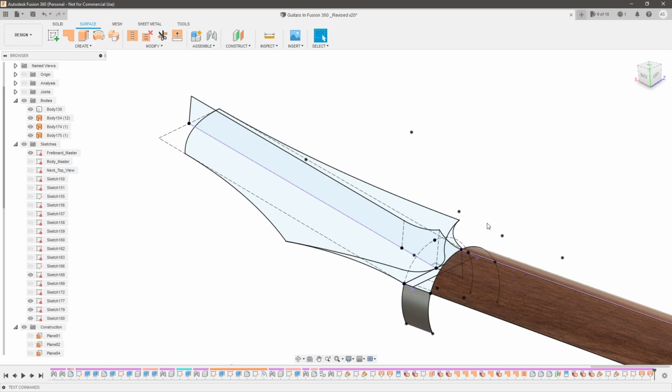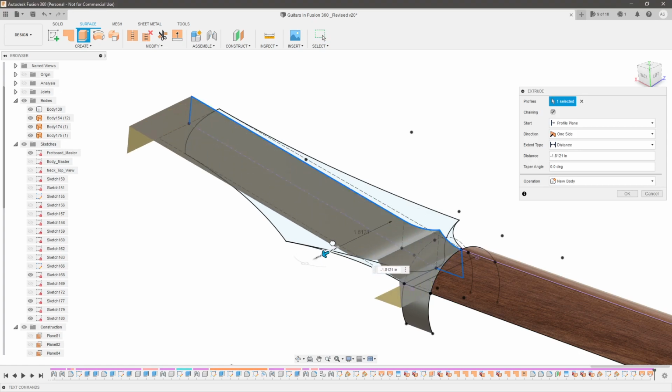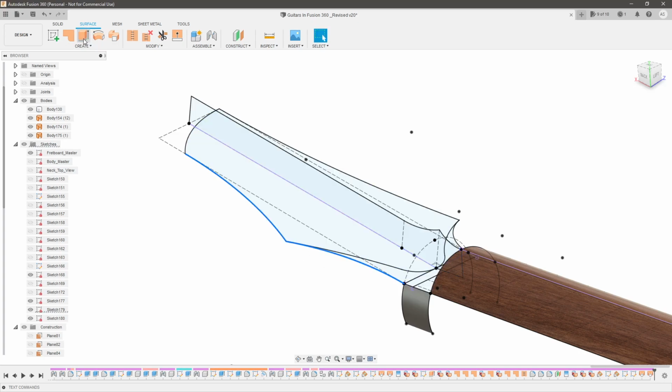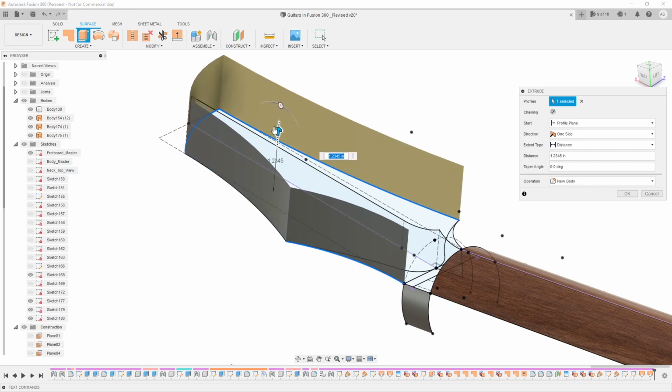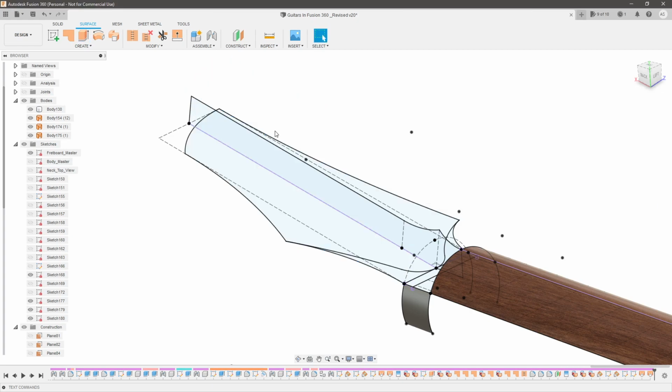In the previous video, I used the intersection curve technique. And I still think that is an incredibly powerful way to give you geometry that you otherwise couldn't draw, like 3D sketches or complex curves, splines, etc. But if we understand the concept of the intersection curve, which is essentially extruding this out and then extruding this up, we can do the same thing with just extruding and split face. So I'm going to show you the same idea, but without the intersection curve.